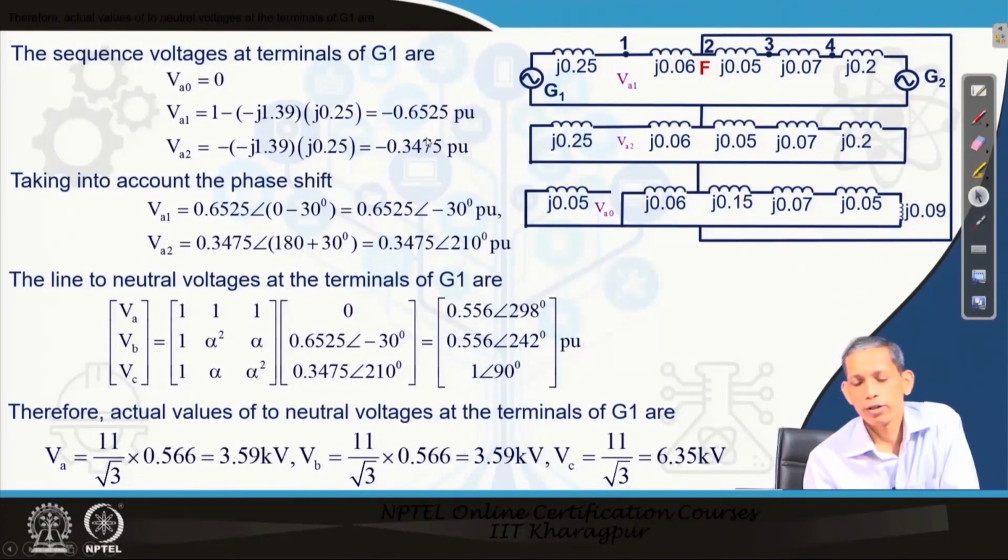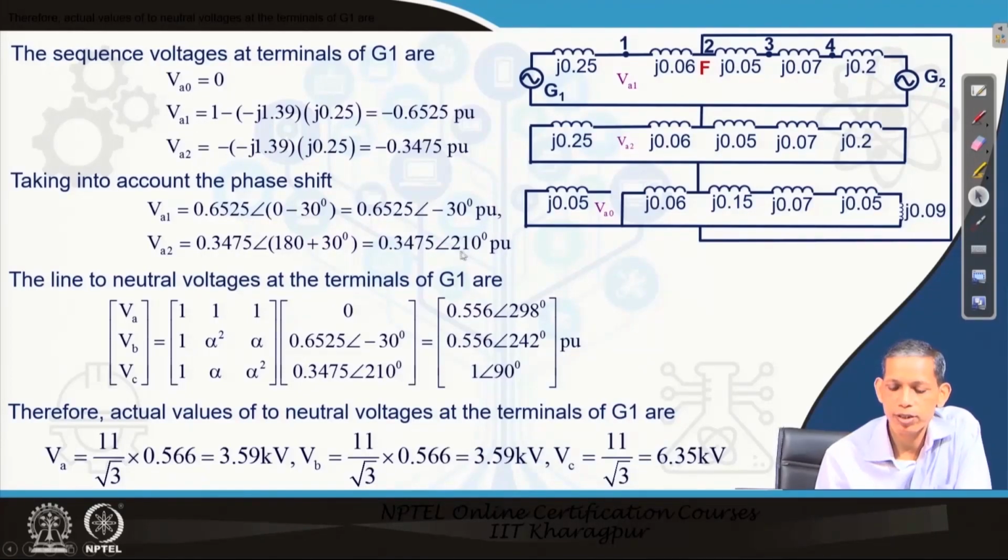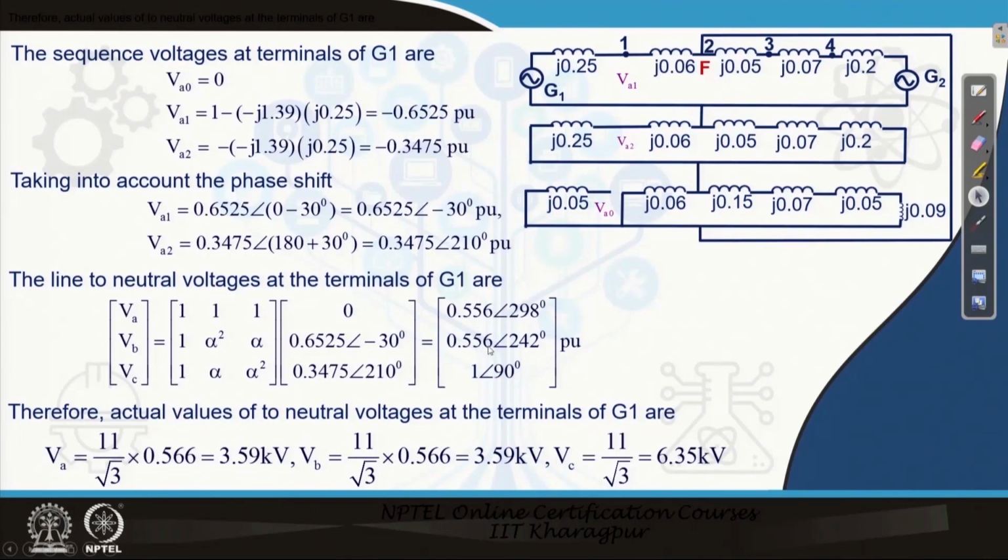Now, in addition to that, as already mentioned, we are going from the high voltage to the low voltage. So, therefore, in the positive sequence diagram we put the minus 30 degree perspective, and for the negative sequence we get the corresponding plus 30 degree perspective. Considering those angles, we get the corresponding VA1 and VA2 in per units like this. Then, to get the phase components VA, VB, VC, multiplying the T matrix to the sequence components, we get the corresponding per unit voltages for this case.